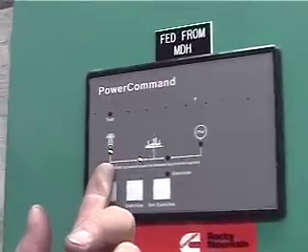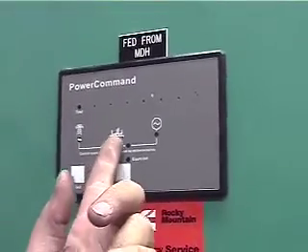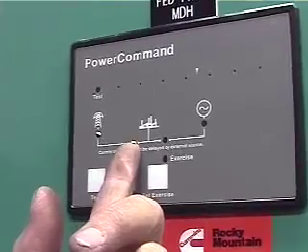That means both power sources are connected at the same time. Physically, unless somebody left a bar out of it, there should be no way it can happen. Right now, this one green light here is the utility, coming from your power company. This here is you being the building, and you are connected to the building.